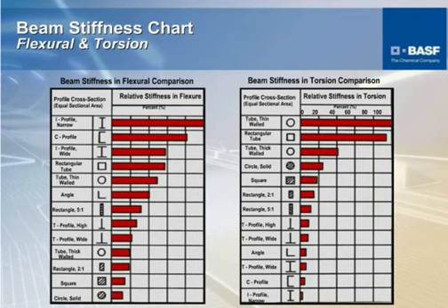Basically, what that means is if you look at the I-beam versus the circular section at the bottom, if you calculate the area of this circle compared to this I-beam, they're the exact same number. All of them, whatever number there are here, have the exact same cross-sectional area. And that's a good way to compare them apples to apples.